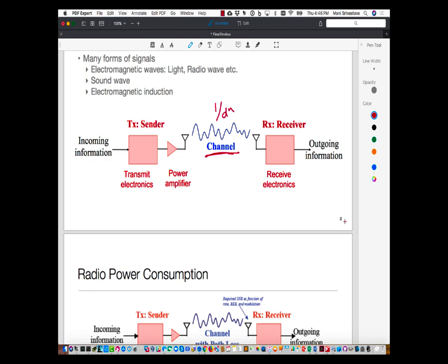By the way, just as an aside, on the midterm, a lot of you just blindly applied that formula, okay? And you got it wrong because in the question I had given you a specific table. So the actual power consumption, I mean, V square F is just an idealization. It's V square F plus the other term which comes as the background baggage. And if you just applied the formula, you're missing that. So in that particular question, the most optimum point was not the lowest frequency, which is the one which would have been V square F. It was actually, I think, number 3 or 4 on the list. So I just wanted to point that out.